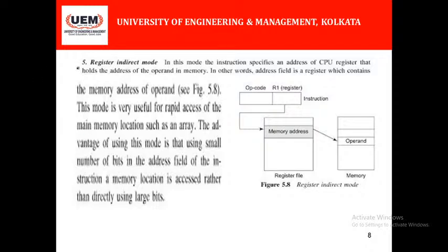Next, our fifth is the register indirect addressing mode. So what is happening in register indirect addressing mode? Suppose LDAX B. Our opcode is representing LDAX. What does LDAX mean? LD stands for load, A for accumulator register, and X for indirect.